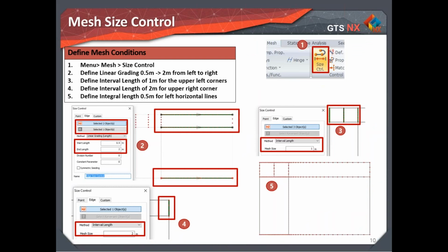Once we have the initial geometry in place, either you imported it or you drew it in, the next step would be to prepare it for meshing. In some cases, you can just go straight to meshing, but in this particular model we want to match the mesh shape. And what we can do within MIDAS is use this command called size control that allows you to get very specific about how the nodes themselves are going to be distributed prior to meshing.